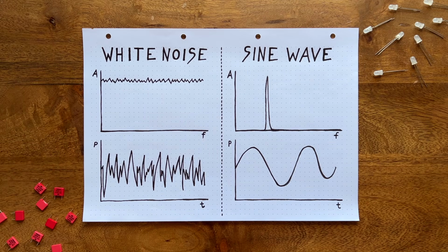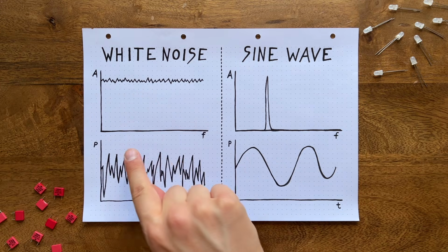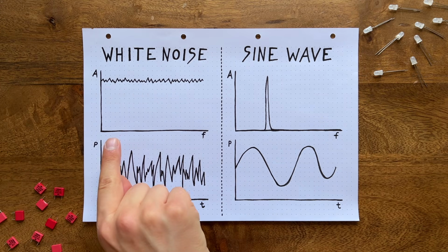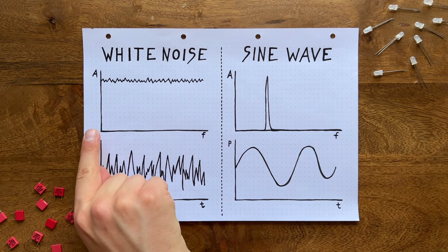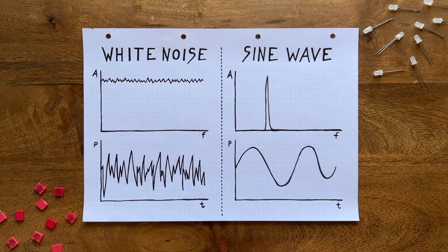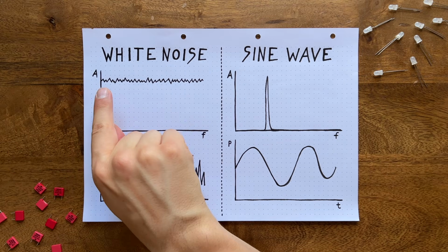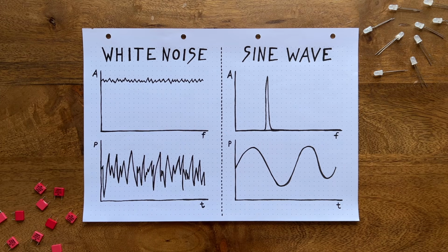So what distinguishes colored noise from any other type of sound? To answer that, let's start off by looking at what's usually referred to as white noise. White noise is a noise that occupies the full range of audible frequencies. To illustrate this, we'll check out a simple spectrogram of a white noise signal, where the x-axis is showing frequency, while the y-axis is showing amplitude. As you can see, every frequency is present here, in slightly fluctuating but generally similar amplitudes.